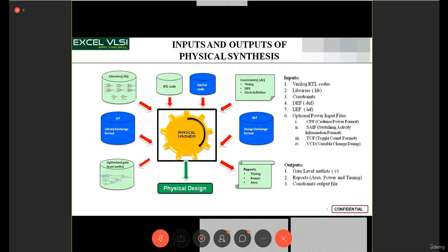In the last session we also explained this. Clock gating is one of the low power techniques which we include right from when you are writing the Verilog code. Now, once you do logic synthesis, you get the netlist. Now the power estimation tools, already you are seeing Genus also will report power. On what basis will it report power? Depending on the switching activity.